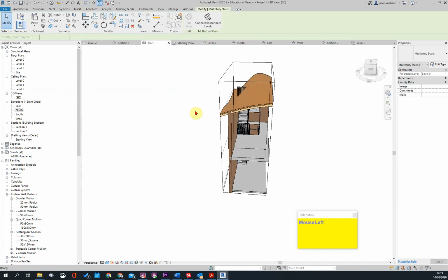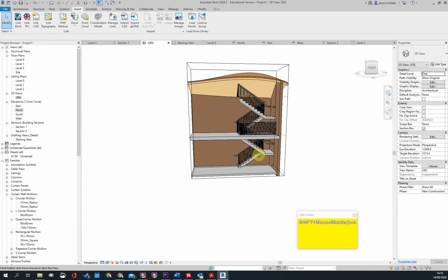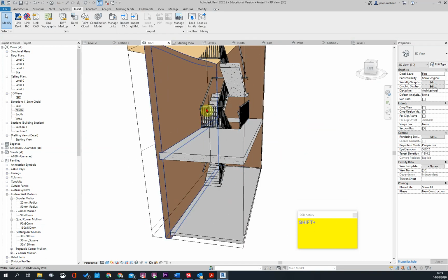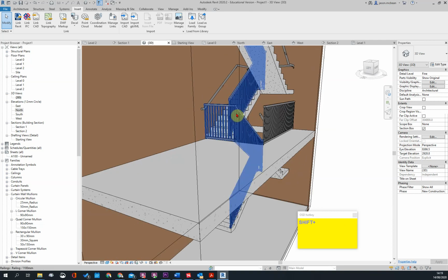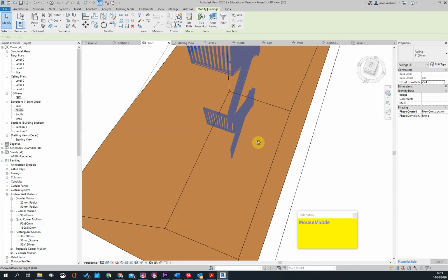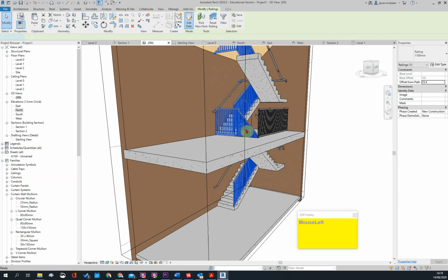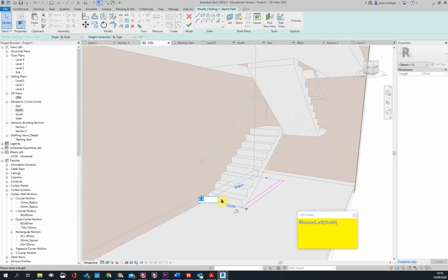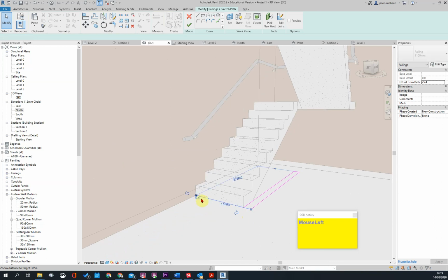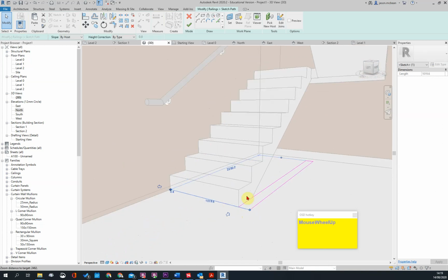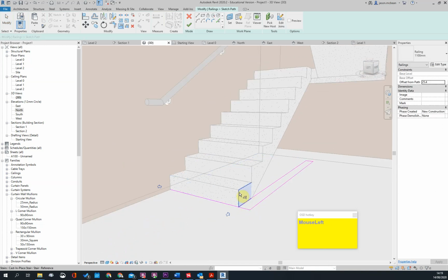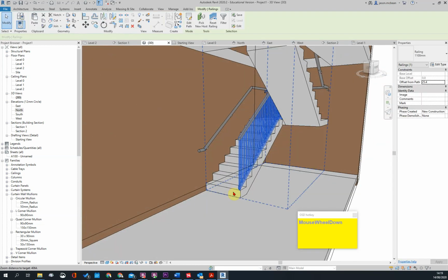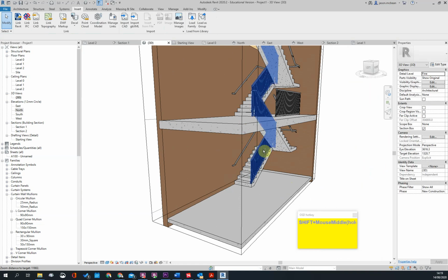If I go to 3D view, it duplicates the stair over multiple levels and keeps all the same settings where the handrailing goes. Okay, here you'll have to adjust this, for example. So here I'll have to edit this path. That will have to stop. This will have to stop somewhere over here. So TS. It'll have to do something like that, for example. There we go.